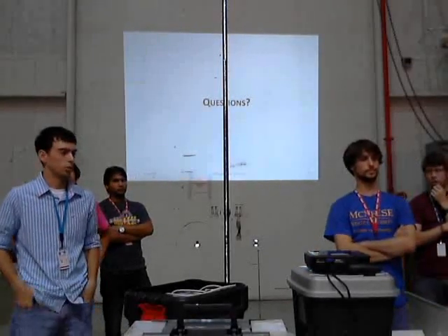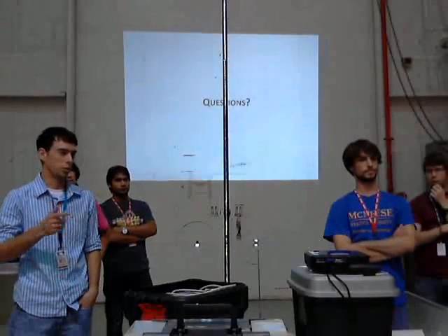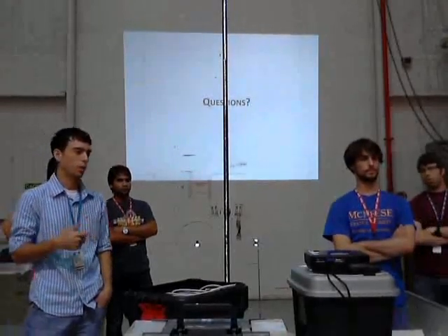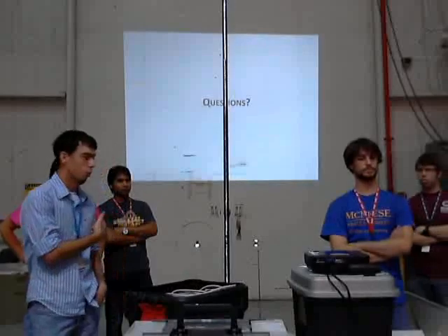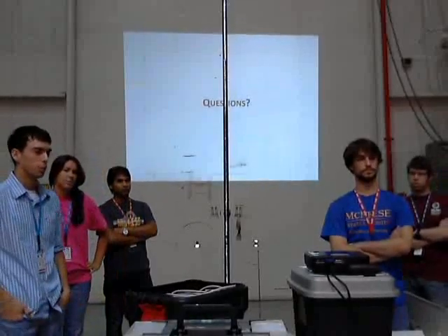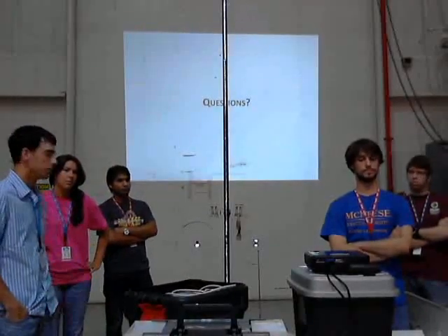You basically switch the switch from a 0 to a 1, and that way whenever you automatically power up the board, it automatically goes into our serial port communication with our computer to deliver the data to a text file.